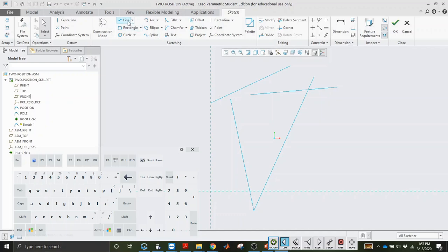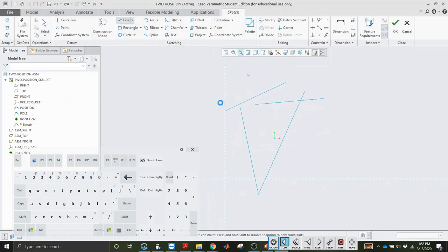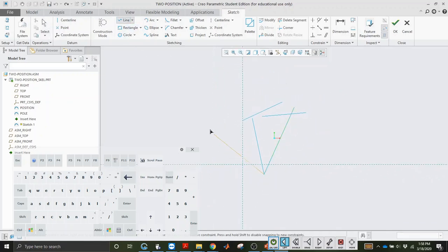Now, if you were to just draw simply, say your moving pivot line wanted to connect here, well, your fixed pivot line is already drawn because this is half your rotation angle, which makes sense because it's half the bisector. If this rotates from here to here by 20, then it only rotates here by 10. But if you wanted a little bit more freedom, you draw one line, you draw your next line. They're separated by 10 degrees.